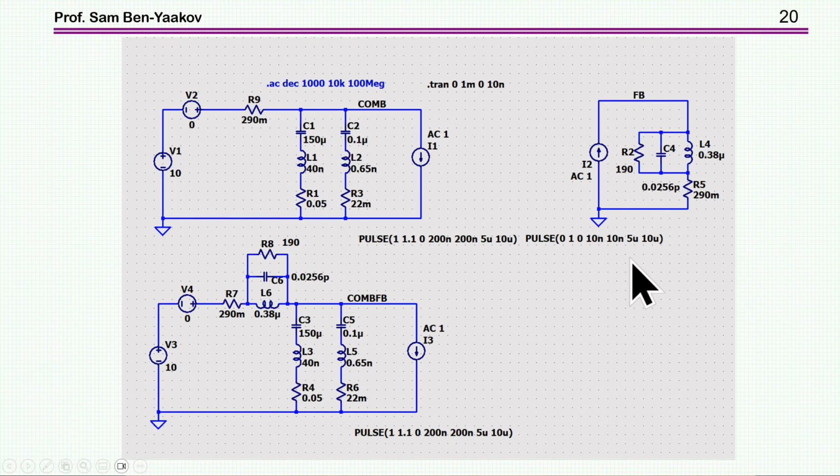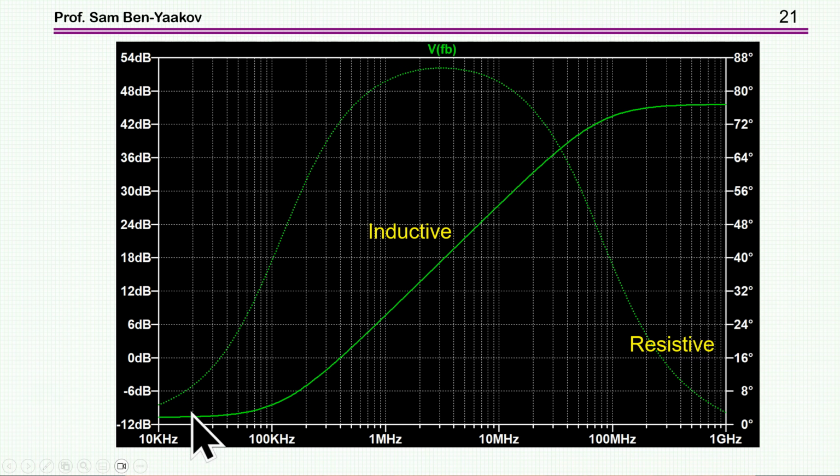But before that, let's have a look at the impedance of the bead. And this I'm doing in an AC analysis. This is now the bead, and I'm running here an AC analysis. And here it is. We see the impedance of this ferrite bead, and then this is the phase. Now, as you can see, the phase here is toward 90 degrees, so it is inductive. So in this region, the bead is inductive, and this region is 1 megahertz to 10 megahertz.